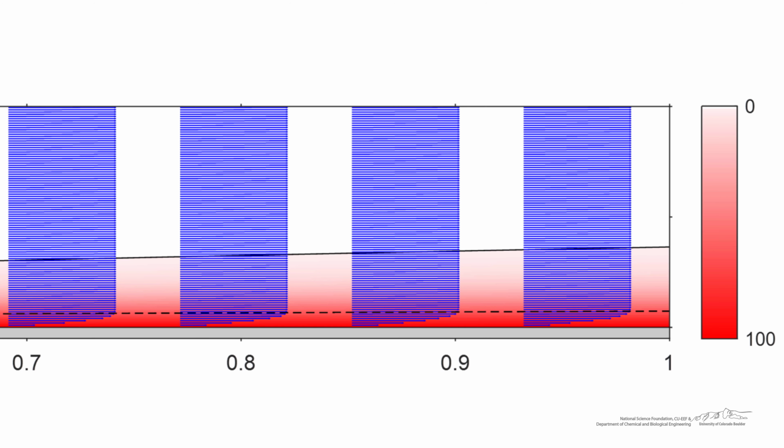If we zoom in on the end of the plate, what we find is that the fluid is being heated up by the plate, but its velocity profile is not being affected. Its velocity profile is not being affected until it's below the momentum boundary layer. So there's a very high diffusion of heat into the fluid, but relatively small impact on the velocity profile.